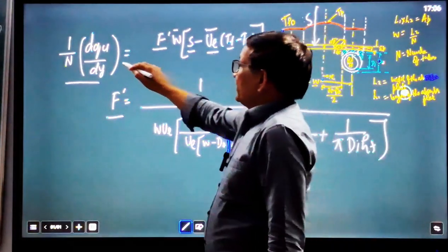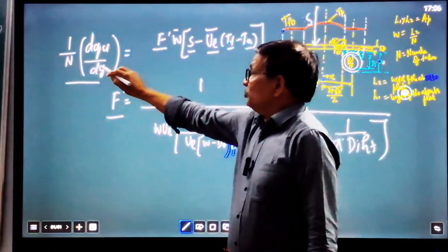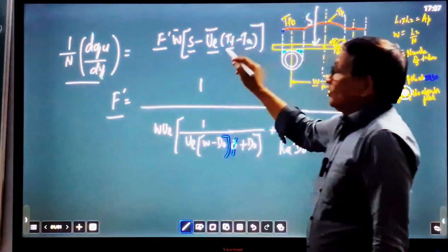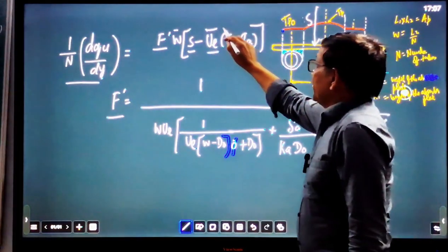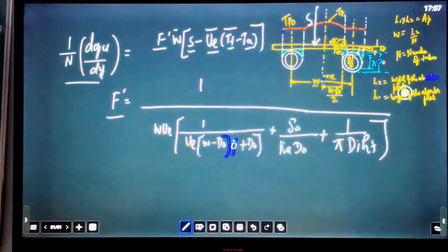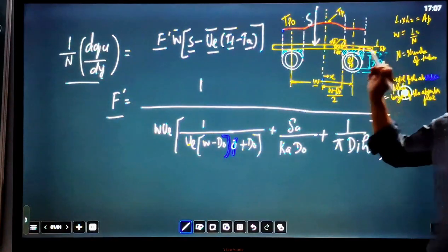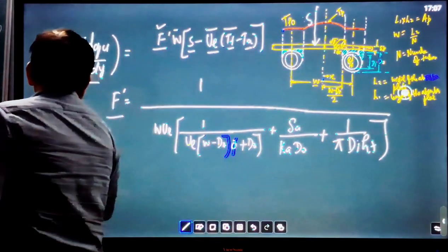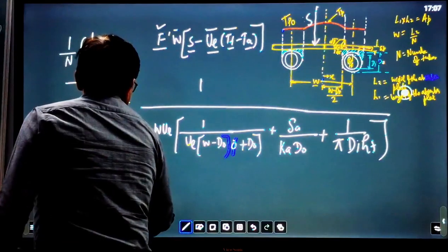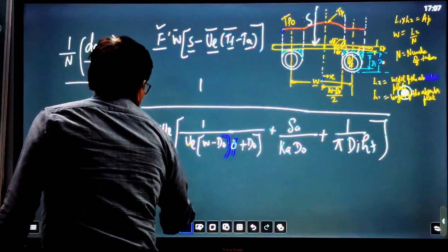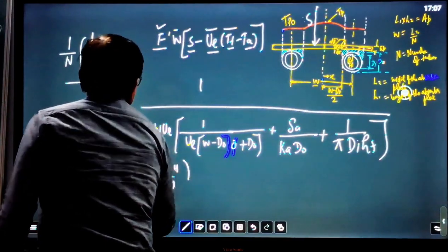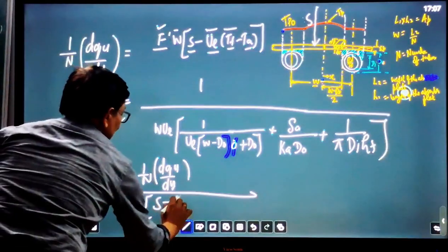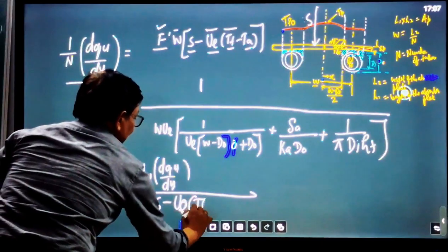It is defined by the ratio of the useful heat gain per unit width per tube to the useful heat gain when the collector plate temperature becomes equal to the temperature of the fluid flowing through the tube. Once again, this factor can be defined as F', because here you can write F' equal to (1/W) dQu/dy divided by [W S − UL (Tf − Ta)].